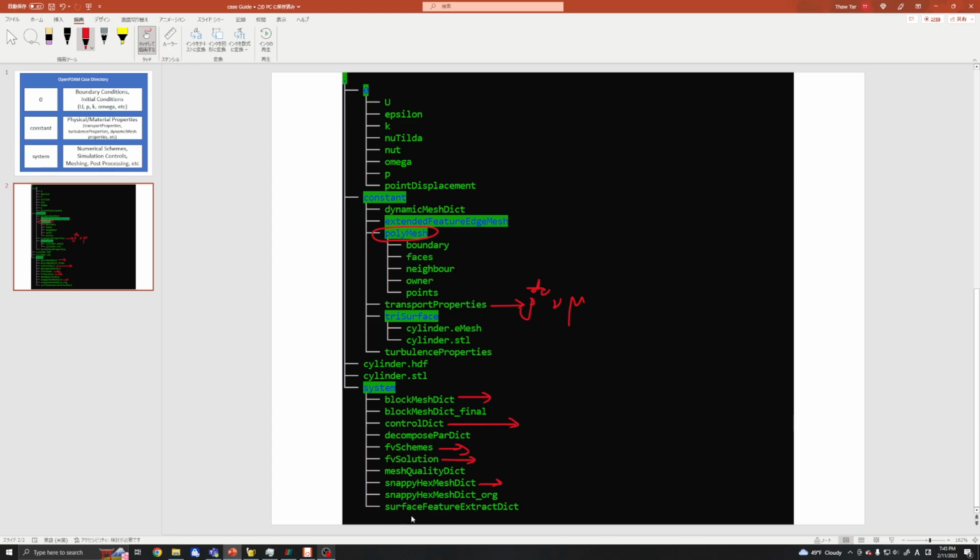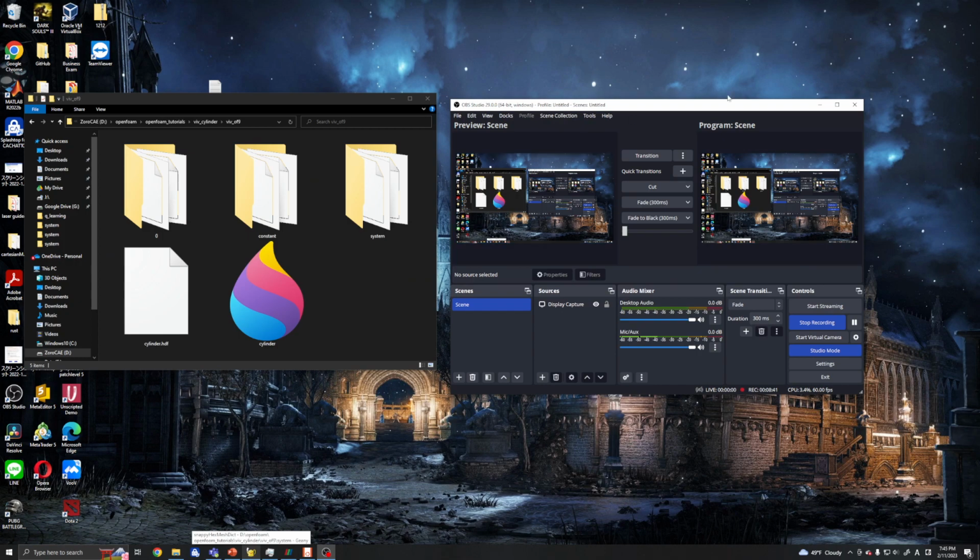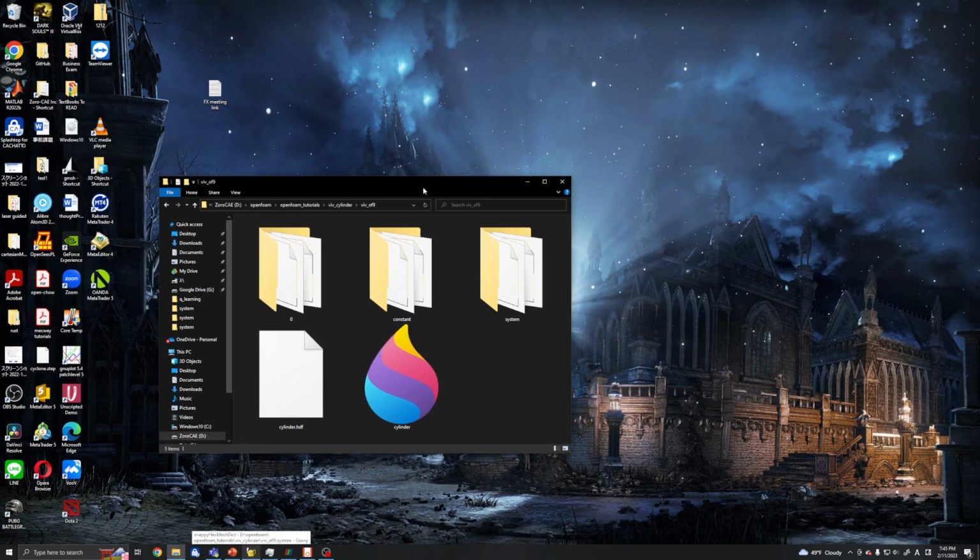And we can have so many other types of files, like for multi-phase flows we can have setFields to initialize our fluid domain, liquid domain, and the gas domains etc., and we can have topoSets to manipulate the mesh etc. So let's go ahead and look at the inside of such a directory.